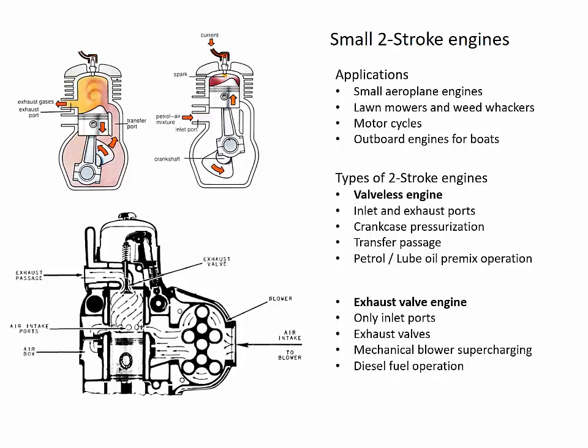There is another, larger type of two-stroke engine. In this particular case, we're looking at a diesel engine with exhaust valves. So it has no exhaust ports, it only has inlet ports built into the cylinder liner, and at the top built into the cylinder head are exhaust valves and the exhaust passage, the exhaust outlet.